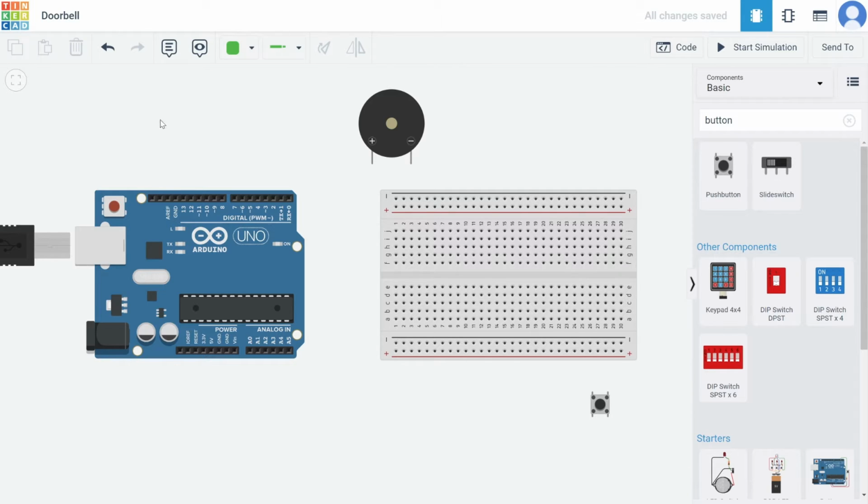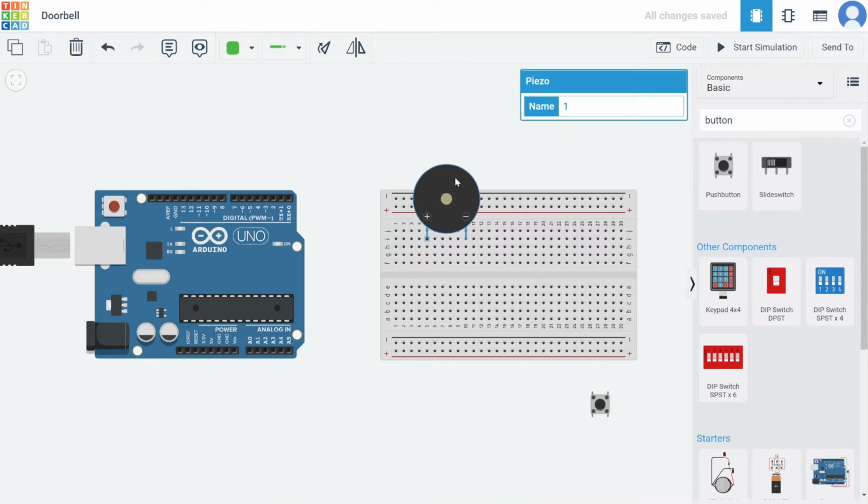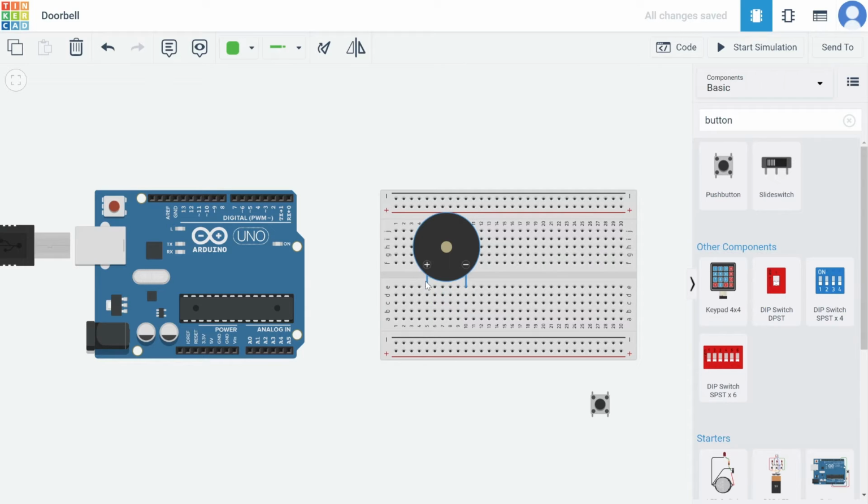let's get going. So what I'm going to do is we need to get the speaker here set up on the breadboard. You could put it anywhere on the breadboard, but I'm just going to put it here, so that, remember, it would be very easy to attach things to each one of the pins here, because any wire that we attach to any one of these 5 holes here, they're all attached, so that will connect to the positive and the negative very easily.